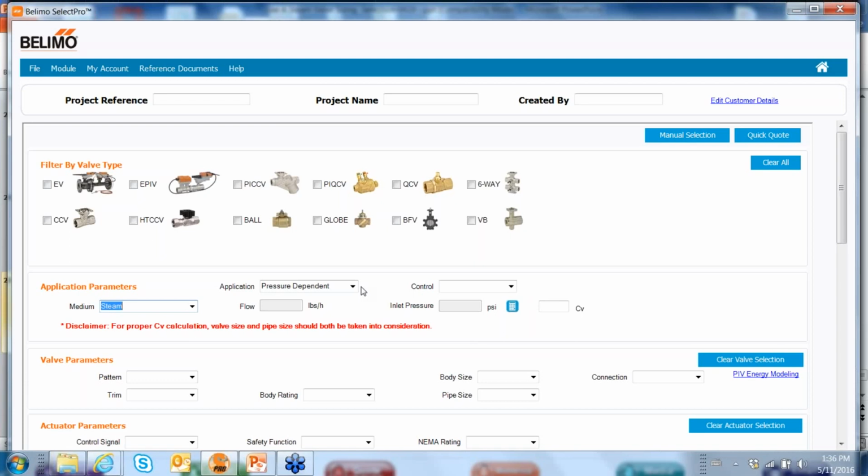If you're changing out an existing valve and you have no information, do the research, or call a Belimo rep, and we'll try to calculate what the existing valve was. So in the bigger product, the 2.5 through 6, it's pretty easy because the CVs are all the same. On the 1/2, 3/4, and 1-inch, it can be a little tricky, but that's all we have to go by. Unless we can get the part number from the old valve, then we can look up the CV. If you have no information, no, there is no rule of thumb.